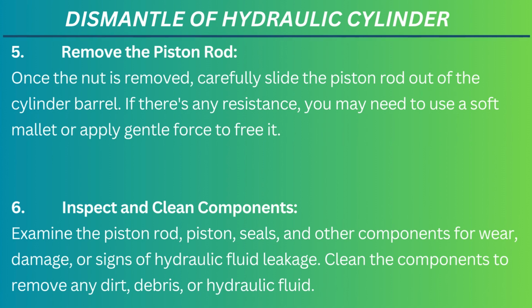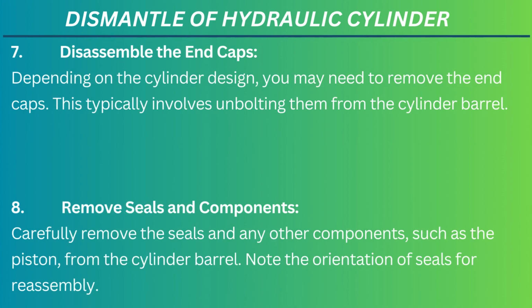Inspect and clean components. Examine the piston rod, piston, seals, and other components for wear, damage, or signs of hydraulic fluid leakage. Clean the components to remove any dirt, debris, or hydraulic fluid. 7. Disassemble the end caps.